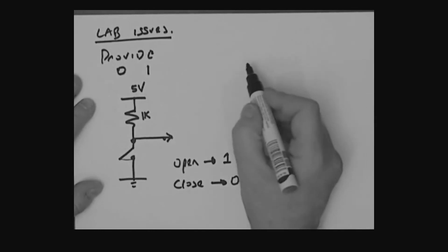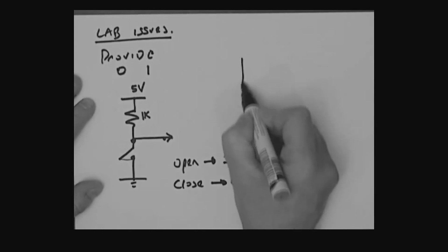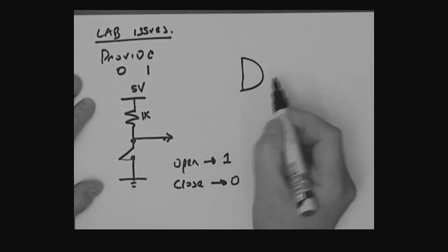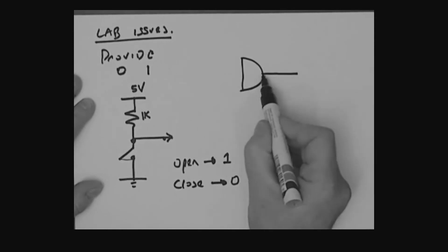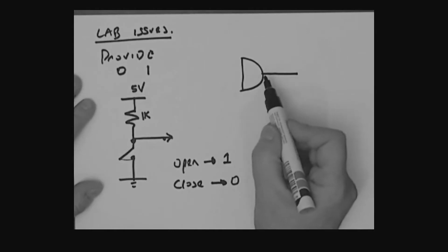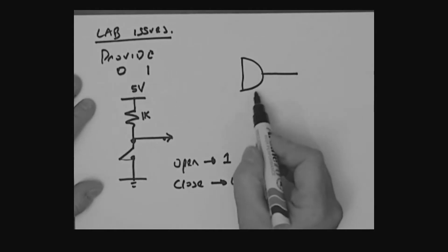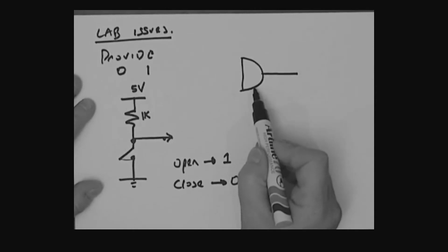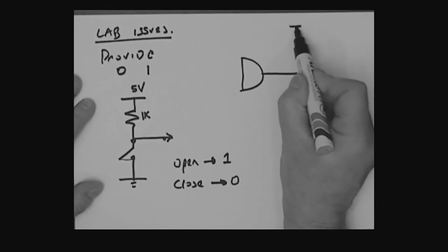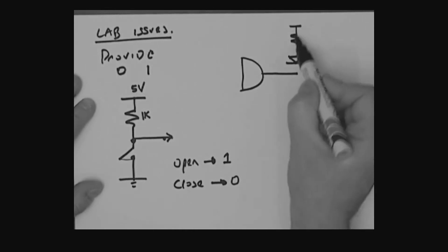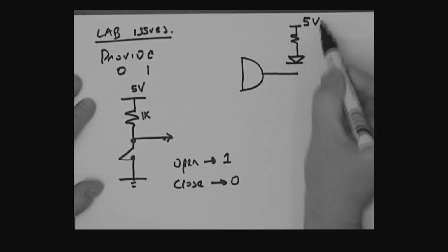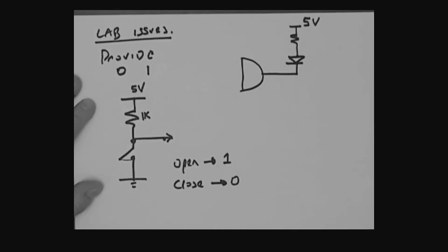All right. Another point I want to make here is outputs, maybe driving an LED. Okay, so imagine that I've got some output here, and I want to basically show that output by way of turning on an LED. Now, the first comment I want to make is that the TTL, which you're using, sinks current better than it supplies current. So the arrangement that you might use would be this, where you have your LED, don't forget the current limiting resistor. This is tied to 5 volts, and the output's connected like so.